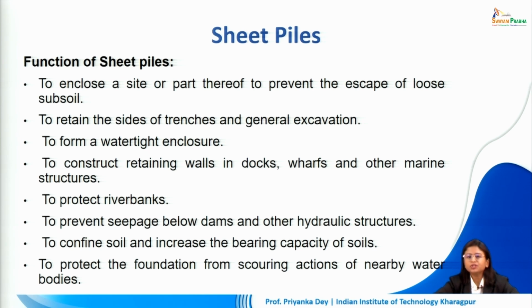What are the functions that sheet piles play? It encloses a site and prevents escape of loose subsoil. It can retain the sides of trenches even when we are doing general excavation for other constructions. It can form watertight enclosures. It can create retaining walls in docks, wharfs or other marine structures. It can protect riverbanks. It prevents seepage below dams and other hydraulic structures. It can help us confine soil and increase the bearing capacity of soil, and also protect the foundation from scouring action of nearby water bodies.